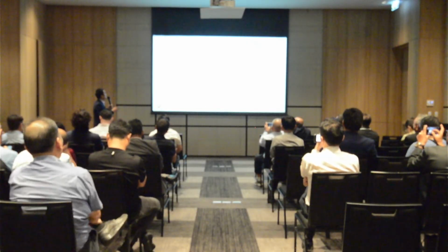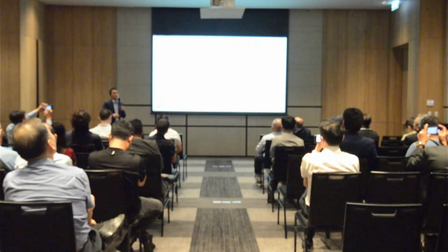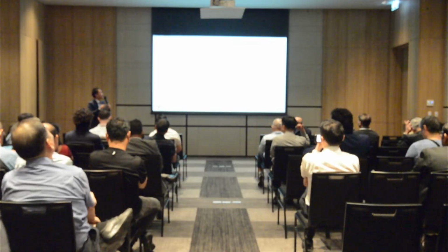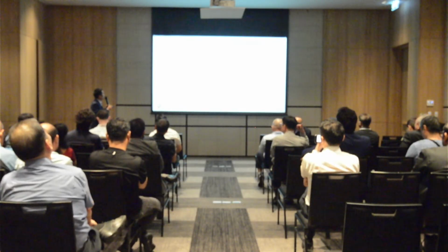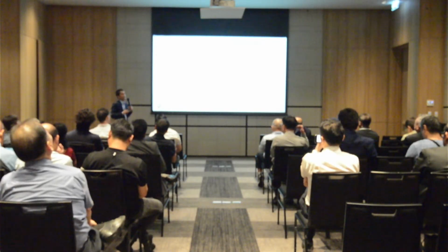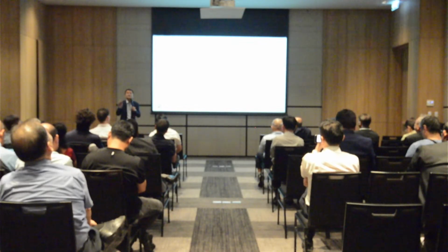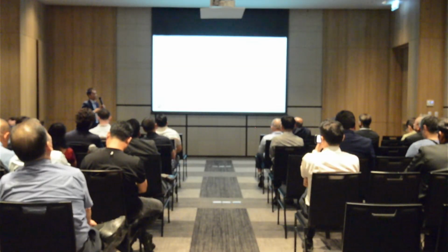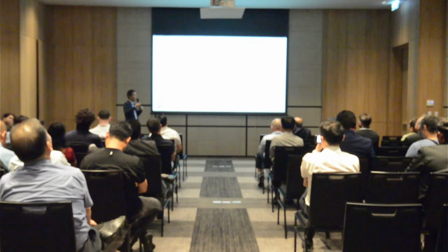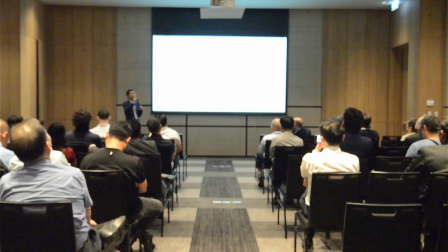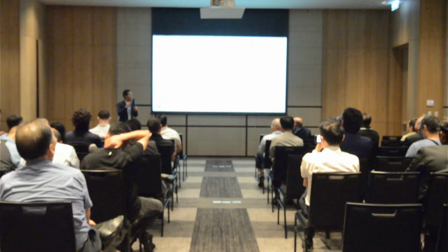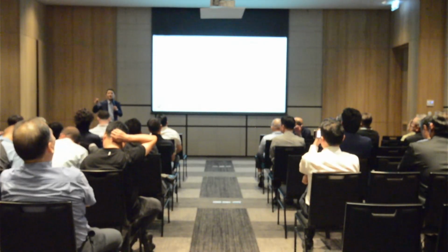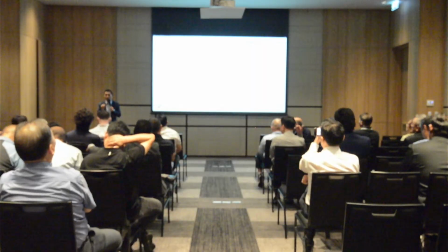The gating system design follows the liquid. It's still like liquid filling, the filling behavior, the direction. That's why it's similar to liquid die design, but we like the gating thickness slightly thicker than liquid gate. Just want to compensate the pressure feeding. And also, the venting thickness is thicker. Why? Because we use slurry, normally for high pressure, the chill vent thickness is about 0.4 millimeter. Normally we can increase to about 0.8 or 1. The bigger venting pushes air out, but you have to put your venting at the right location.